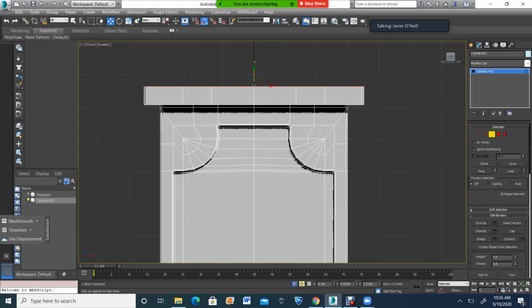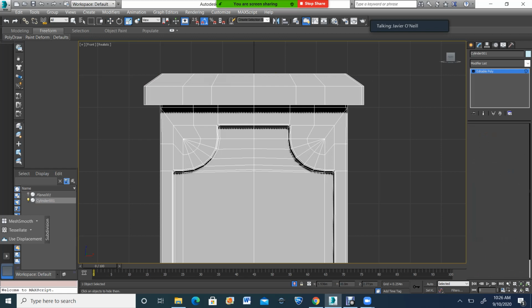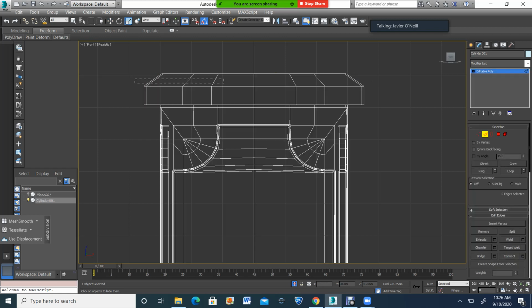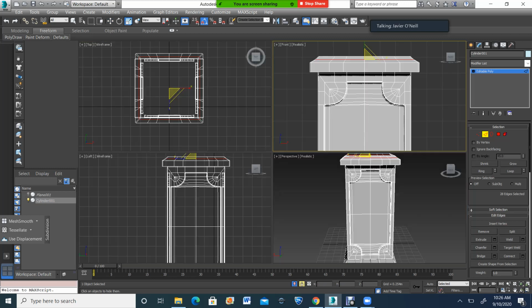This is the part where I'll just do it how I like. So one more extrusion, and take that extrusion, lower it like this. I want this to have a sort of gradual curve right here. So I'm going to press 2 for edge, select all of these, Control Shift E, space to lock my selection, scale this down a little bit, cool, I like that.